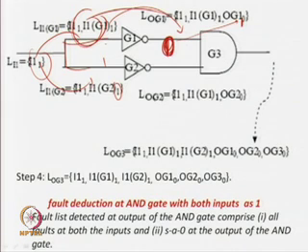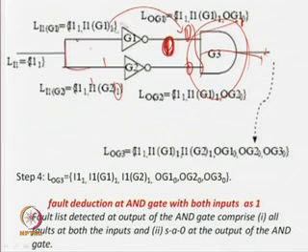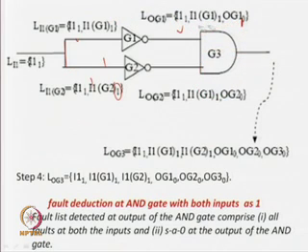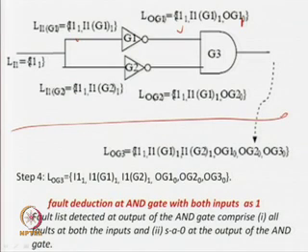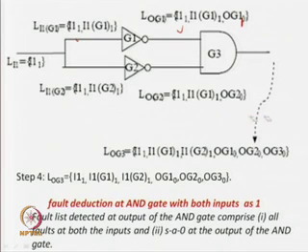And then similarly we have seen the rules for an AND gate. If the case is 1 1, then whatever fault lists are at both the nets will be added here, plus some stuck-at-0, stuck-at-1 at the output. If it is 0 0, then only the common set of faults between these can propagate to the output. So we are studying rules in deductive fault simulation, where if you scan the circuit from input to output, you can find out which faults can be detected, but for that we require some rules. In the last lecture we covered some rules, for example, if it is a fanout net, whatever fault list is here propagates here.